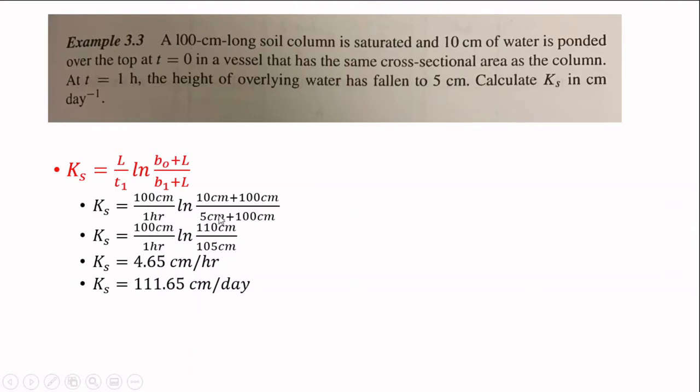So you can use that to calculate. In the end, you get the saturated hydraulic conductivity. The saturated hydraulic conductivity is equal to 111.65 centimeter per day. Okay, so I hope there's no problem to convert 1 hour to day.